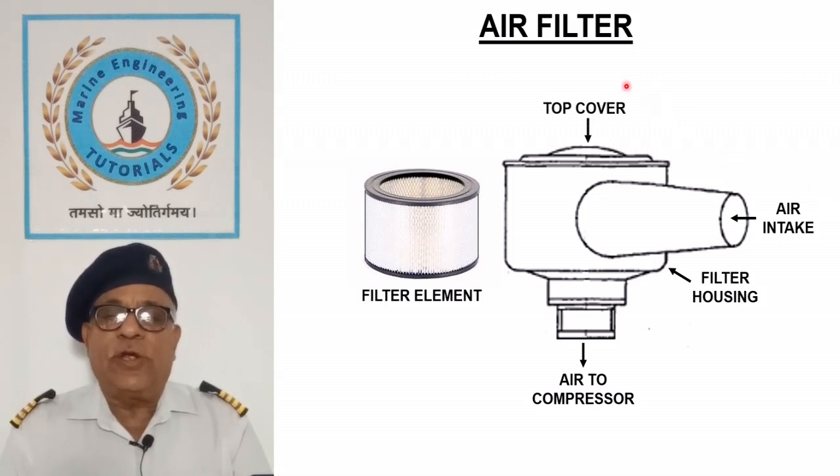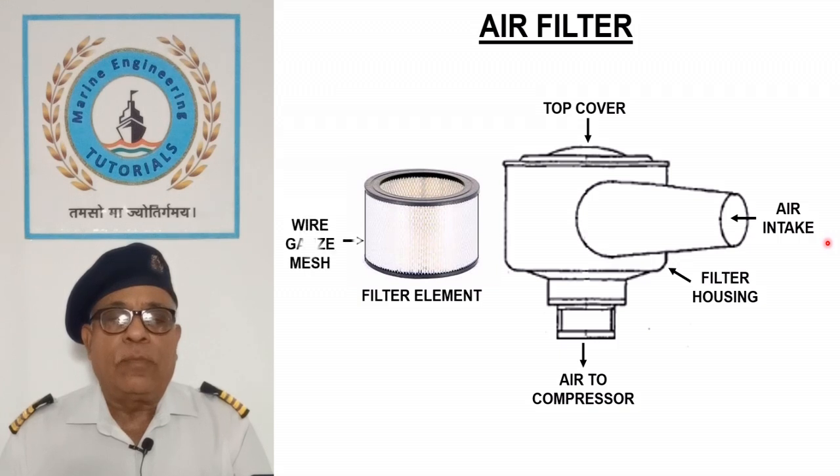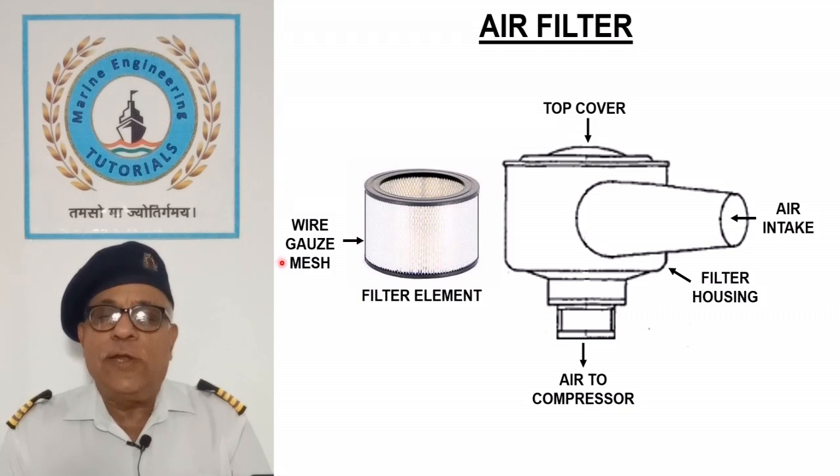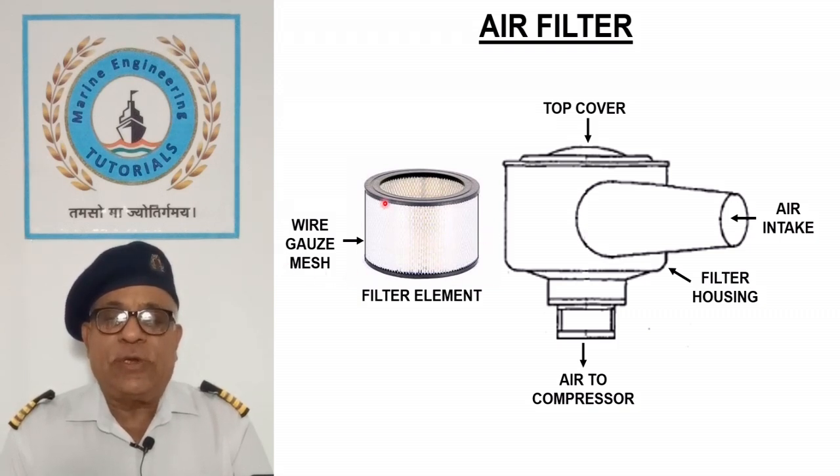Filter element is inserted through the top cover. Filter element is made up of closely knitted wire gauze mesh which is periodically cleaned by blowing compressed air backwards.